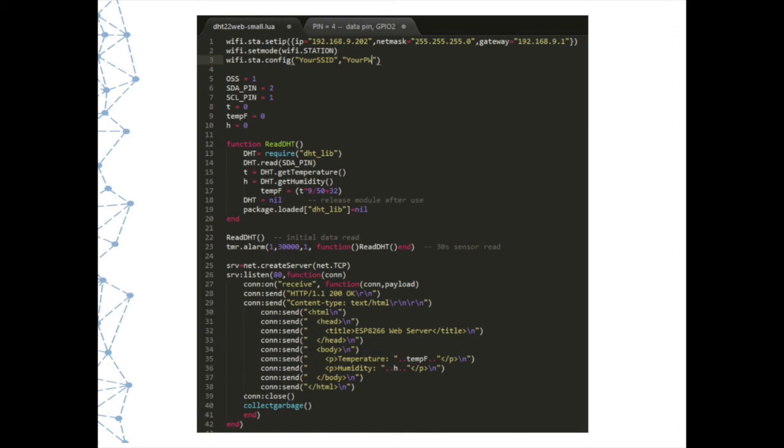I've been working on a project where I wanted to send out syslog. Just as there is a web server set up, there's a UDP service that's built into the stack. So I can enable that and send out UDP messages on the syslog port 514. So there are super flexible ways that you can work with these things and build what you need out of them.